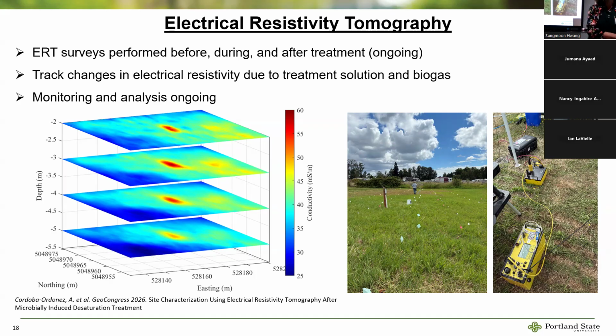There is another issue in terms of the amount of gas you need to desaturate the soil as it gets deeper, because the steady state pore pressure is higher. It'll compress the bubbles in the nitrogen, because that's the best way to say it. So you need to generate more nitrogen to get the same level of desaturation, because you have a higher